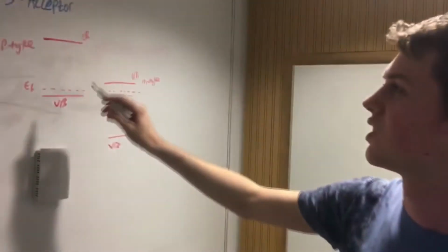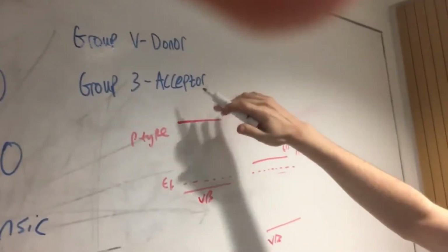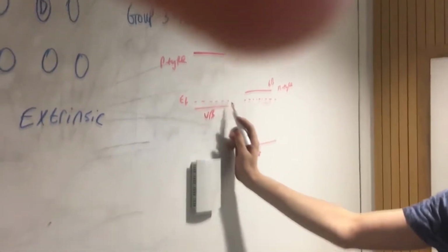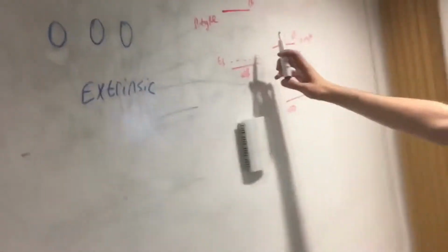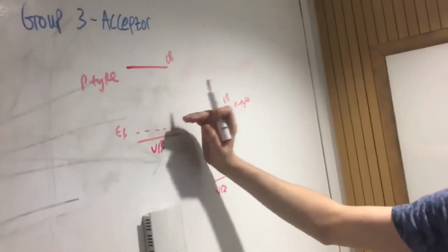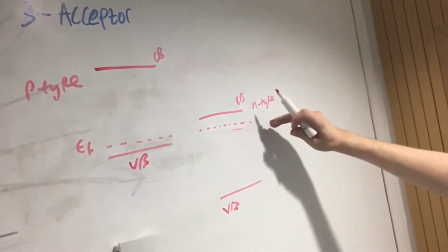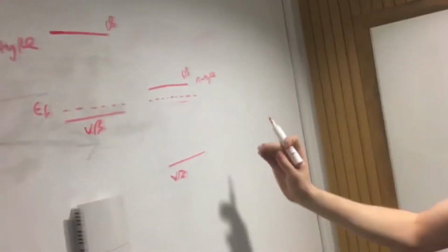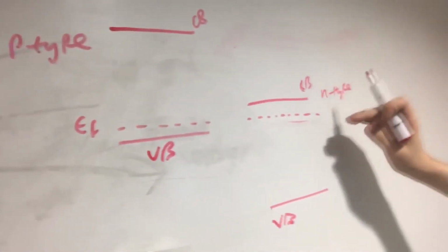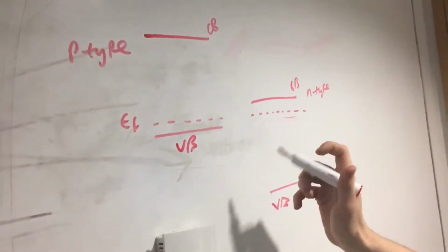So, we have a p-type, which is denoted by the type that are electron acceptors, where their Fermi level is lower than what we have mentioned over here, because there is a low chance of electrons being free and being in the conduction band because there is an abundance of holes in the p-type, whereas the group 5 dopants cause this n-type to form, where the Fermi level is higher because there's a higher chance of the electrons being in the conduction band in this material.